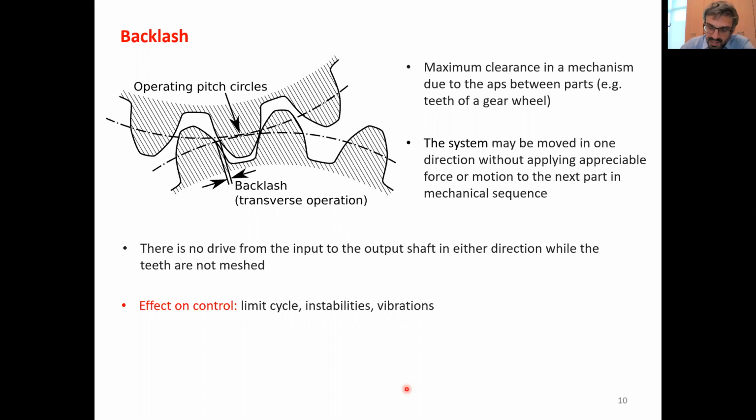If you have backlash in your system, you should try to remove it, because there is no control strategy that can help. You have under-actuation, you lose actuation at some moment, and whenever you have feedback control, the lack of actuation is very detrimental. The only solution is to improve the mechanical design. Try to use conic gears, try to improve the geometric tolerances and machining of your gears, in order to remove the backlash.